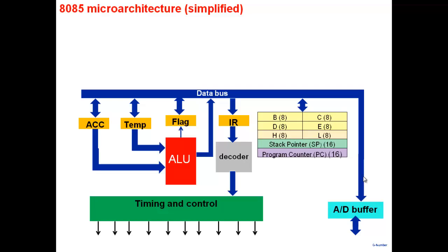So what it does is the data bus, the pins that are associated with this data, it shares with the address. Okay, so you'll see in a minute what happens. For example, the program counter contains a 16-bit address for the memory here. The red one is the address part here. Usually when you're driving external circuitry, you add buffers here. Note that we have 8 lines here and 8 lines here.